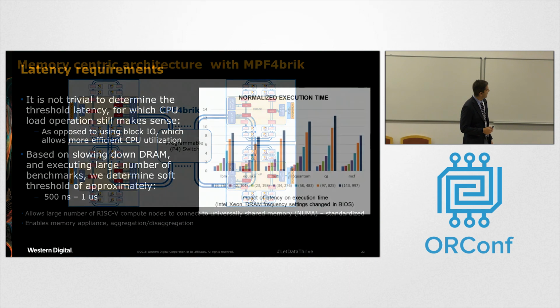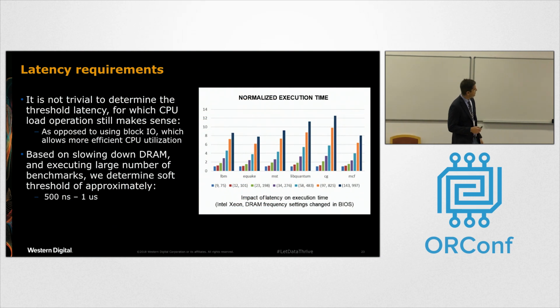The latency requirements, we did a lot of measurements to try to understand what is needed, and this is an interesting topic on its own. I would like to have time to write a paper on this: how many nanoseconds you need on a memory to call it a memory. The reason is that a 3 microsecond memory is not good enough today because you can build a block device in the 1 microsecond range. So for something to be a memory, it really needs to break the microsecond barrier.